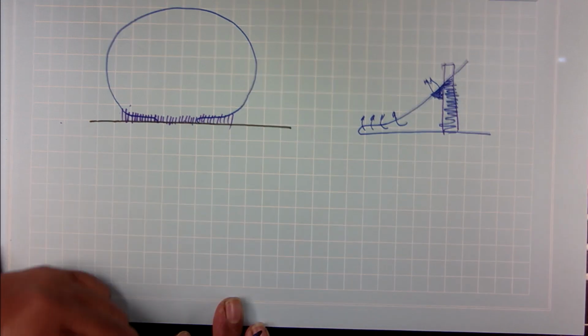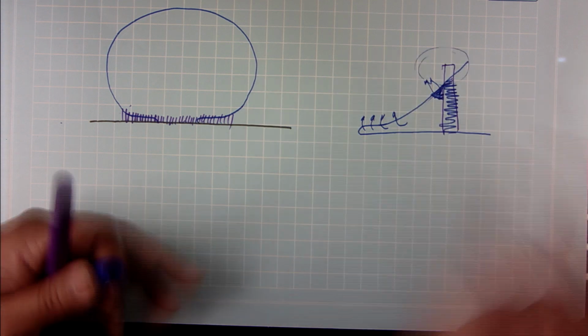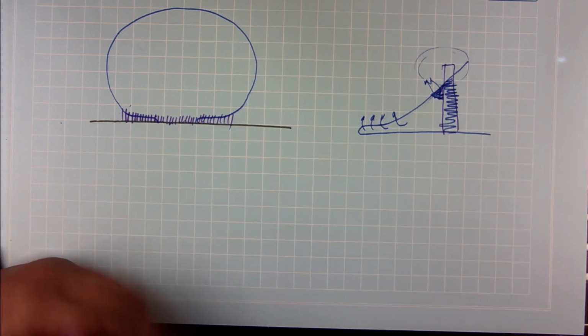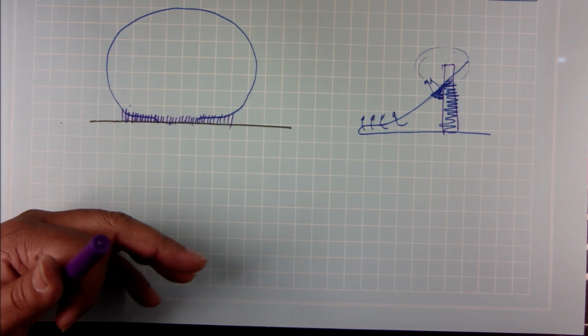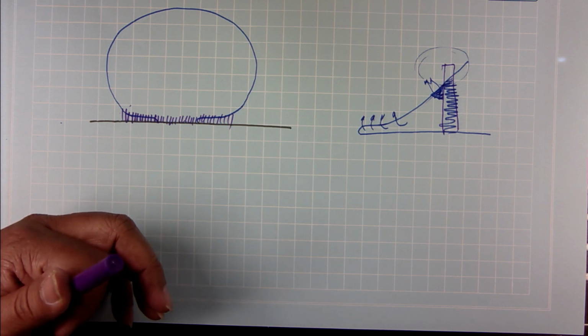After that it is not participating anyways, because the rest that is sticking in the vapor bubble is in an insulated region. So, it is not helping with the heat transfer anyways. So, that explains the 100, 200, 300 giving you the same CHF.